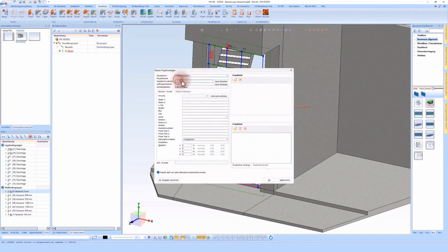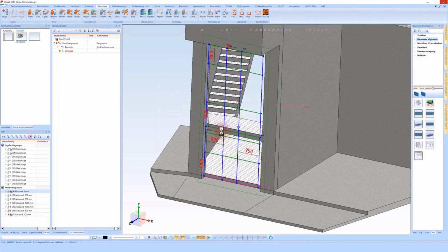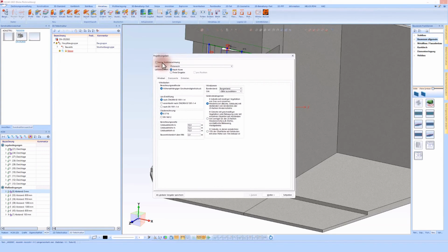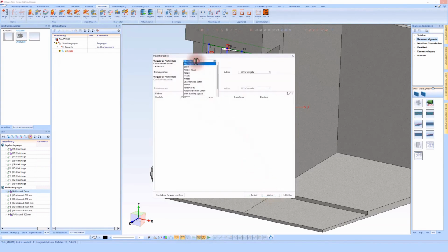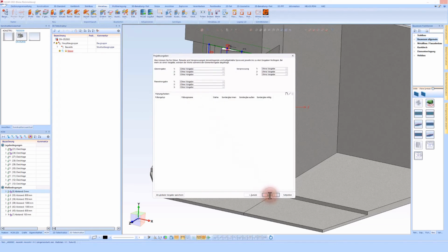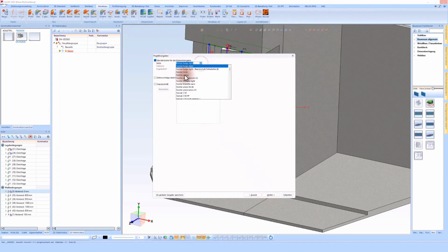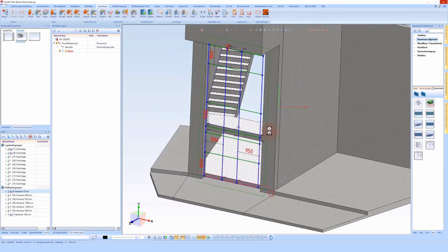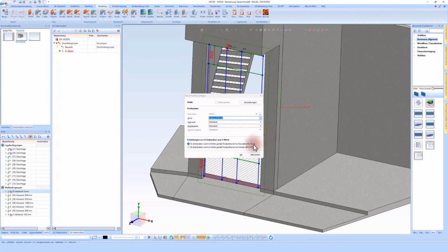Here I can define my folder and I want to enter a project name, Entrance Facade Family Huber. So of course here I am inside Logikal and I enter my conditions here. In this case, I do not want to perform a static calculation. Here I can already set my specifications, which means I want to stay with Schuco here. I can also define certain surface colors, which I will do right away. Glass specifications, I don't care about that now, which means I still specify which series, then I don't need to select anything else. Thus, I have now created my element or my facade or my project in Logikal, and now my position is already being created.